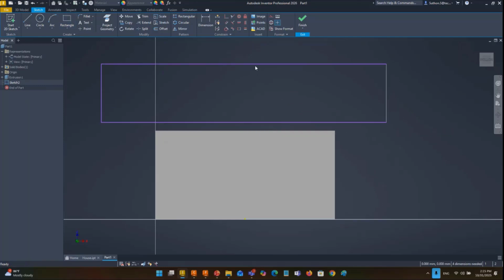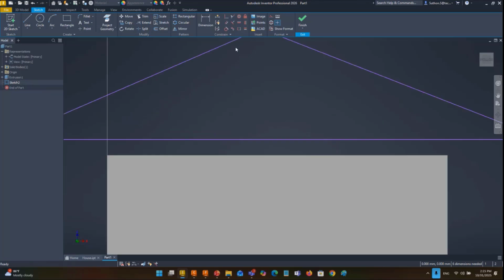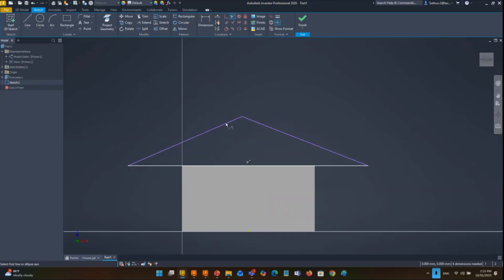And then we want to get rid of this side and try to destroy the parallel function and make this one go further to meet each other at the middle. And then I use the alignment tools to make this one coincident on this line, and then I dimension it here from here to here about 8 meters in length.